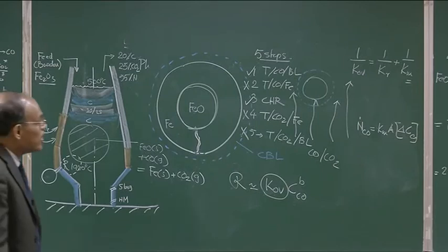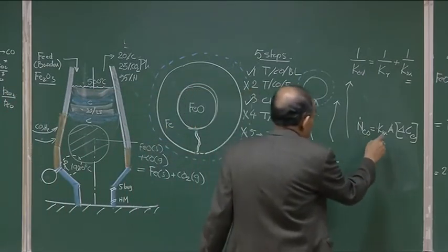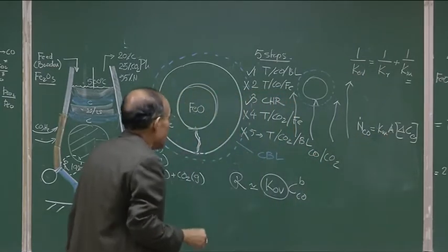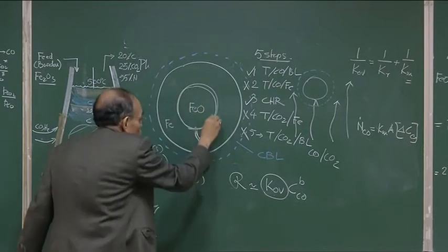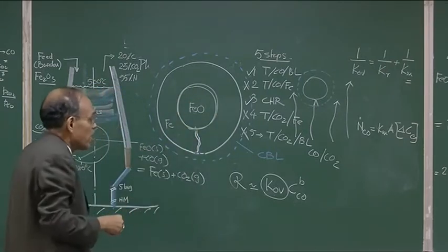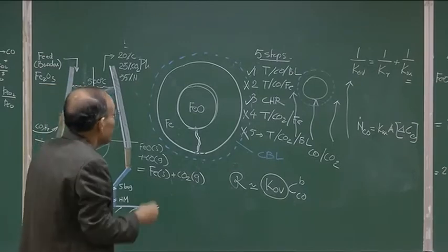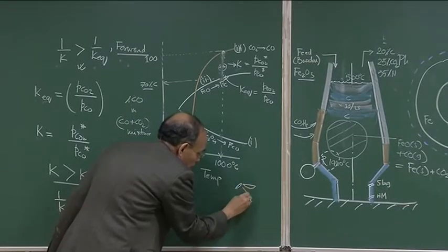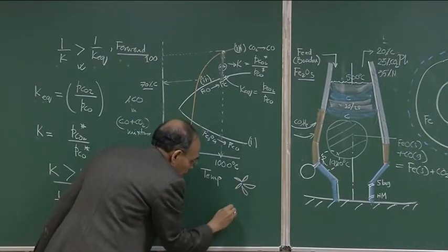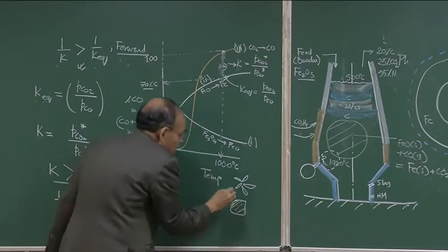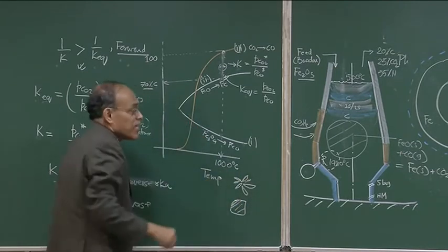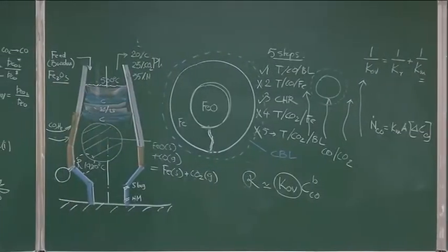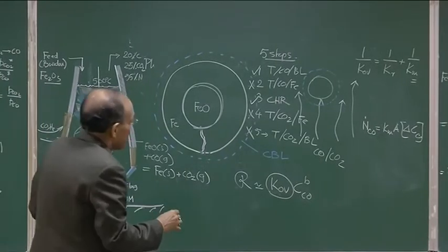So, therefore, we can see that the surface area comes into the picture, and similarly the heterogeneous chemical reaction also takes place on the surface itself. So, the surface area is an important parameter, and that is what we see when you have sinter particles like this, which are joined together. Rather than having a lump, what we have basically done is create more surface area, and as a result we have been able to get more reduction, or a faster rate of reduction.